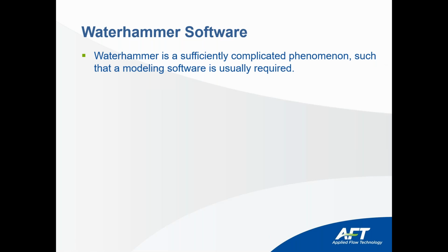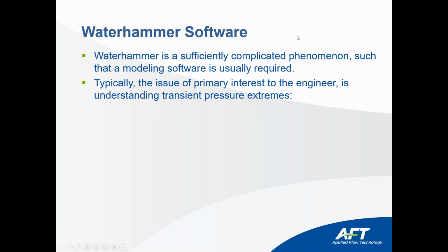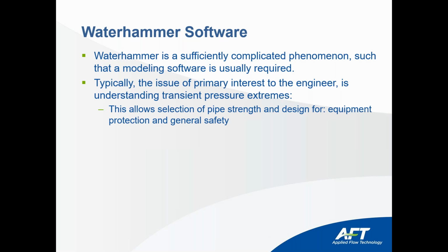Waterhammer software. Waterhammer is a sufficiently complicated phenomenon. It's not easy to model, especially when you have a pipe network. And in such cases, a modeling software can be very helpful, and it's usually required to accurately model the Waterhammer event. Typically, the issue of primary interest to the engineer is understanding the pressure surges, how they are generated by the pressure waves.